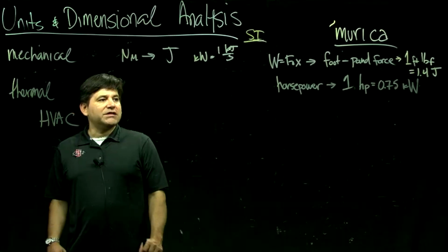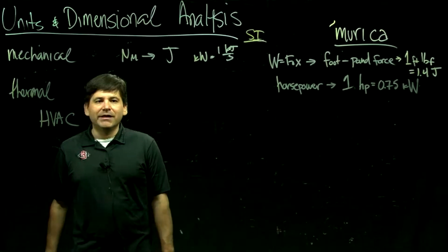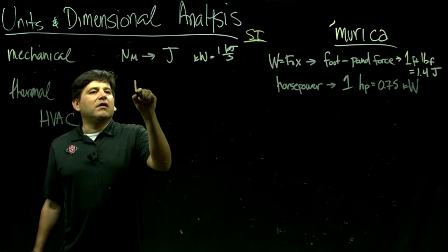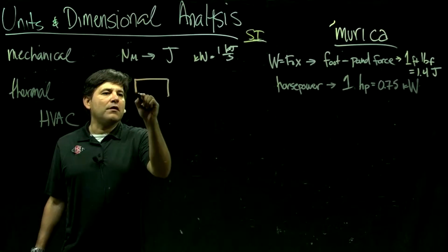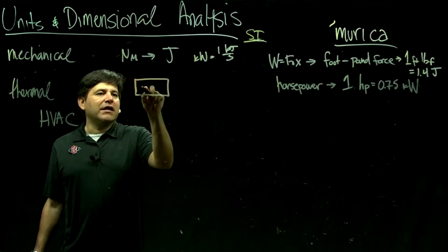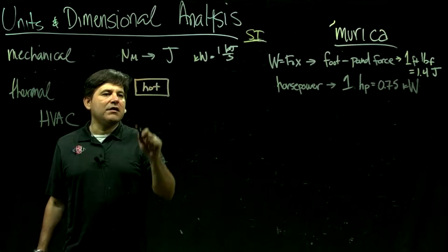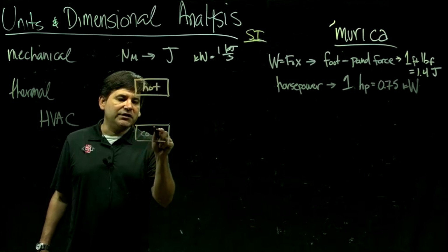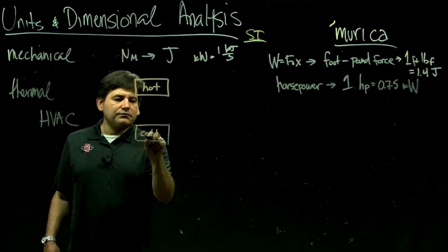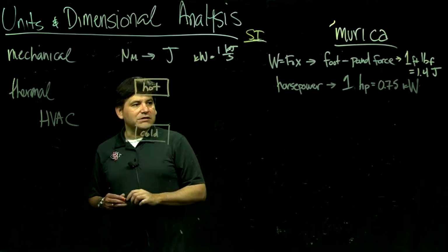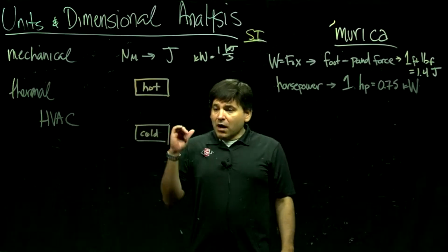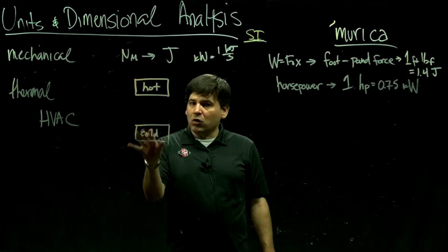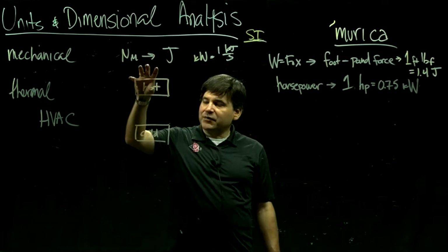And the standard that we still rely upon is the vapor compression cycle, which is one type of reverse heat engine for heating and cooling. And a simple diagram of a refrigeration cycle, in terms of how it works as a reverse heat engine, the simplest schematic would be you're operating between a cold reservoir or some cold temperature and a high temperature.